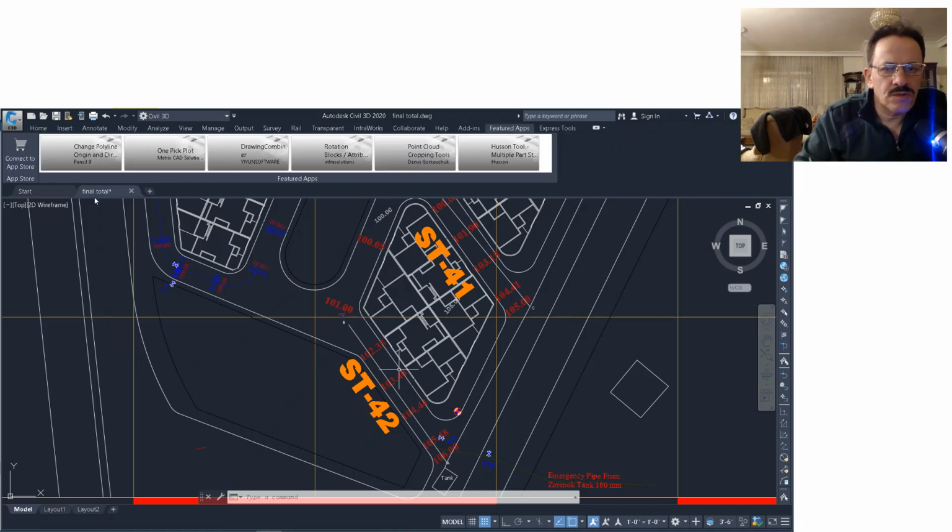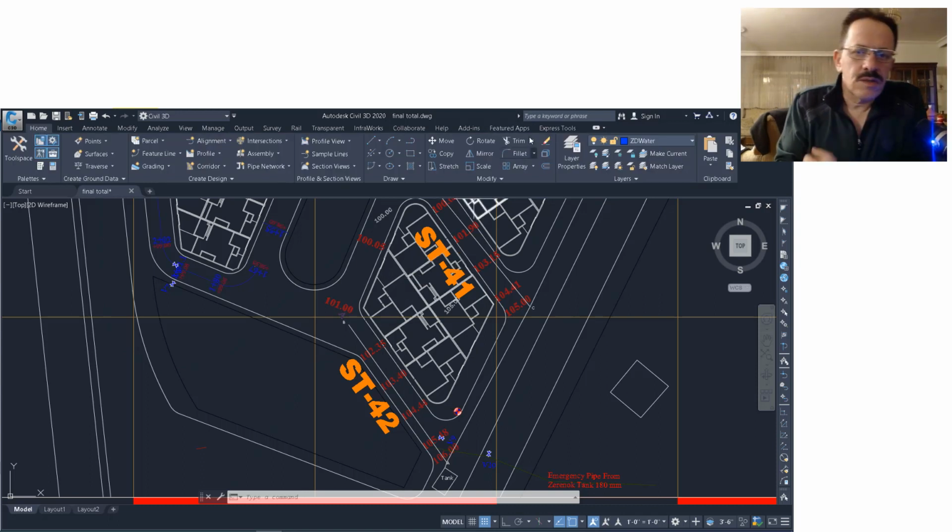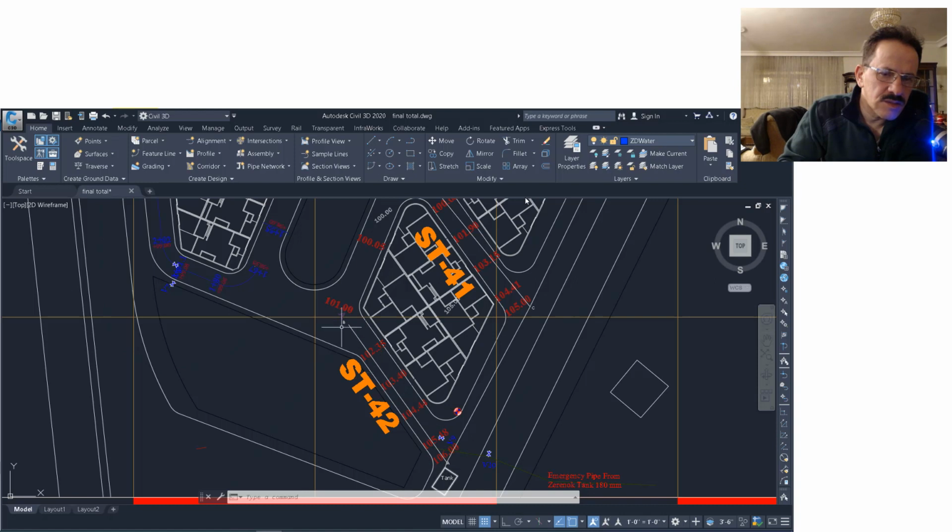So you have to draw all the pipes here, and by the way, the head in this pipe, the head at point A and the head loss from A to B, the length is here. So how to find the head at B? Just the head at A minus the head loss will give you the head at this one. Now I'm done with the water work.